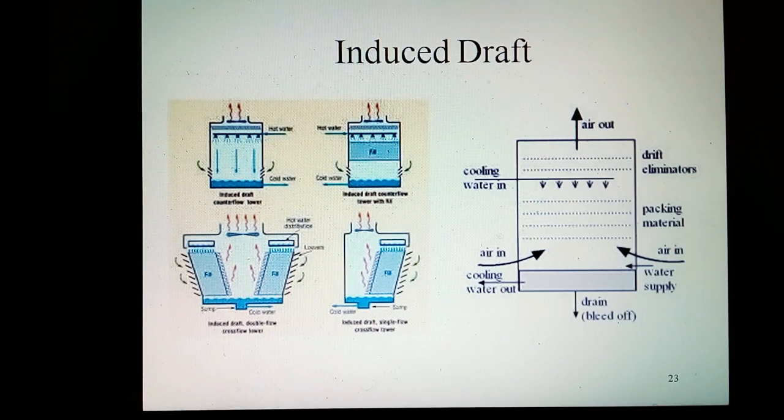Cooling rates of mechanical draft towers depend upon various parameters such as fan diameter and speed of operation, fill for system resistance, etc. Mechanical draft towers are available in a large range of capacities. Towers can be either factory built or field erected. Concrete towers are only field erected.